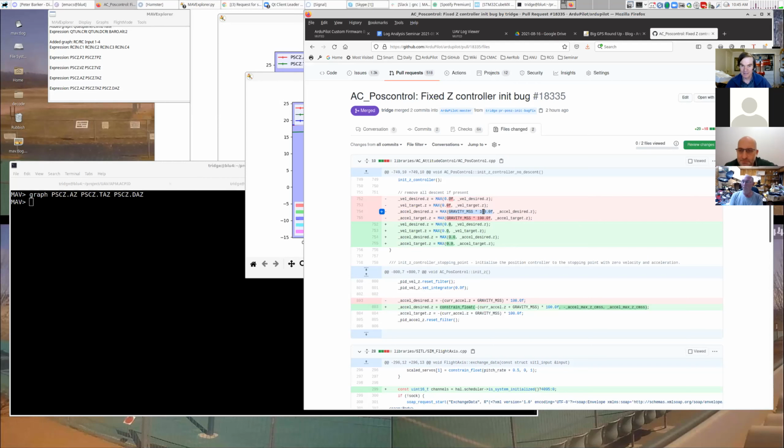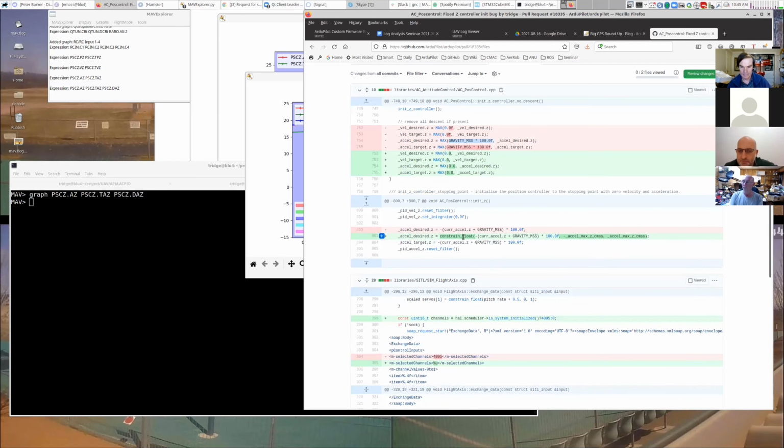Question: You're obviously constraining the initial values here, but where's it getting those? The 2G vertical acceleration, it's getting it from the current acceleration. So it's just the IMU, and it's actually the blended earth frame acceleration, which comes out of an EKF estimate, which is really just a smoothed and blended estimate rotated into earth frame. So it's basically your IMU. It's your Z.